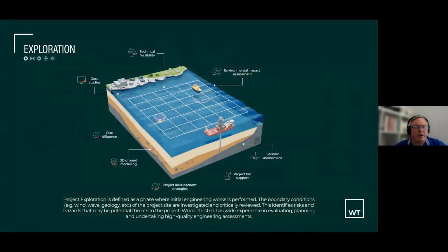So just to give a sense of some of the details of the exploration here, we would typically have some sort of buoy that would be able to gather mid-ocean data. There'd be a current measuring device on there, wave measuring devices, as well as what we call a FLIDAR, which is the acronym for floating LiDAR. LiDAR being the device that uses light to determine the velocity of the air based on the speed of the particles that are traveling through the air. And a FLIDAR is simply a LiDAR that's on a floating platform.